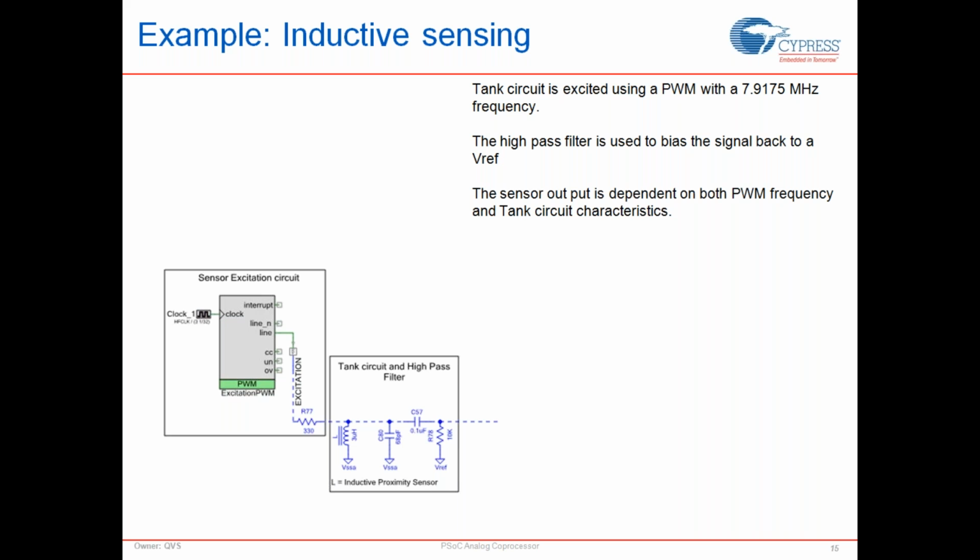So 1 out of the 32 phases of the clock, I'm going to have 1/4 of the divider, and 31 of the other phases, I'm going to have 1/3 of the division. So effectively, over the entire phase of 32 clocks, I'm going to get a 3 and 1/32 division to the clock.